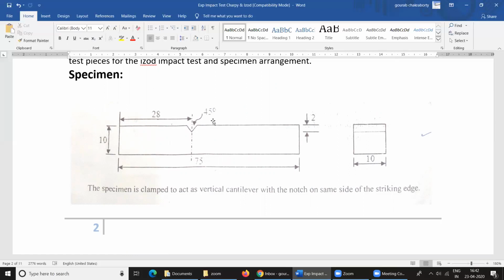The main purpose of the notched bar tests is to study the simultaneous effect of the stress concentration and high velocity load application. In impact tests, the fracture may be either brittle or ductile. The brittle fracture is not accompanied by noticeable plastic deformation. This type of fracture will have a bright granular or crystalline appearance. On the other hand, considerable plastic deformation takes place in a ductile fracture. The fracture surface will have a dull gray fibrous appearance.